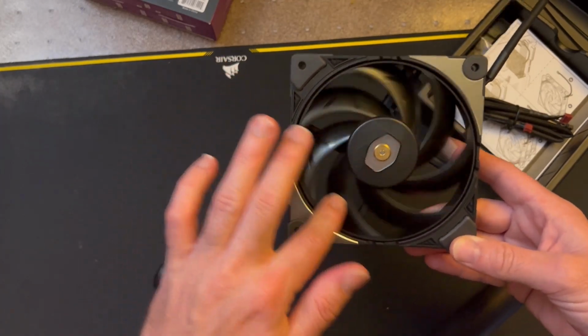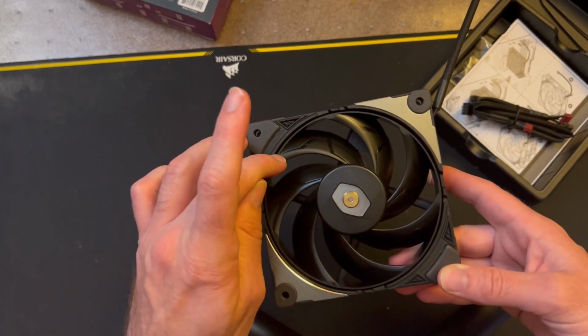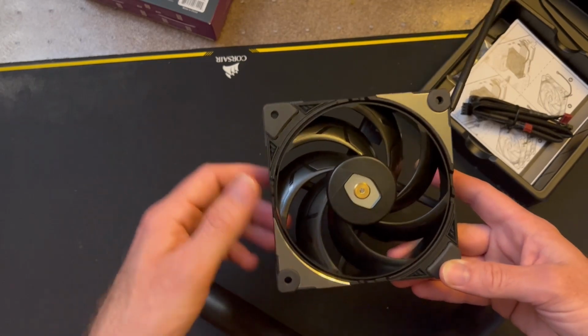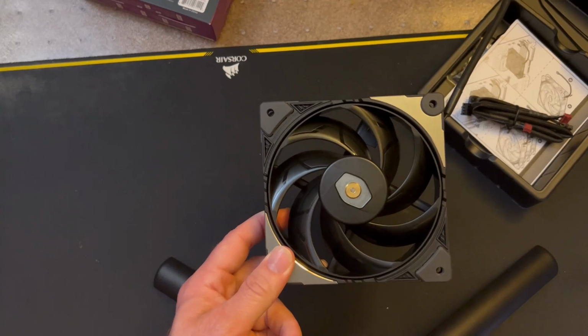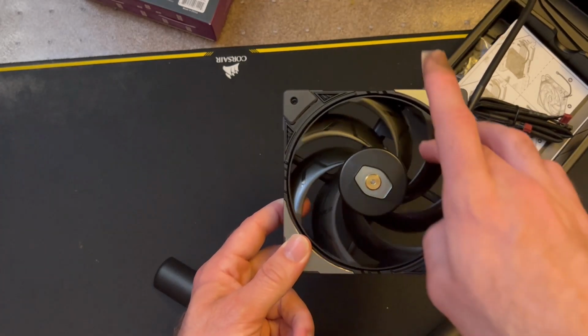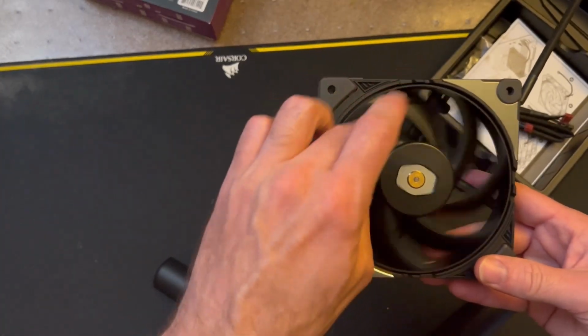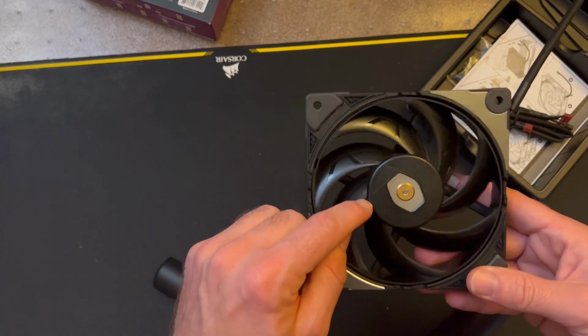The downside of having that ring is it makes the fan heavier. So if there's anything wrong with it, any weight offset or anything like that, it's going to transmit more vibration because it weighs more. So there are advantages and disadvantages. It means that it can't achieve an RPM without a stronger motor. And stronger motors are more expensive, and you get into this cycle.